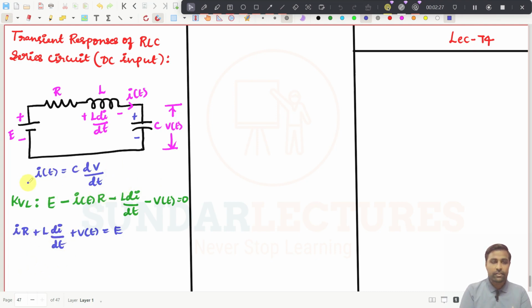You will get RC dV divided by dt, and then plus L times C, so LC, d by dt of dV by dt. That gives d square V divided by dt square, plus V of t, which is equal to E.